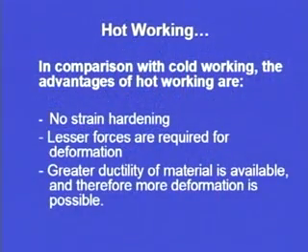Now, hot working, in comparison with cold working, has the advantage that there is no strain hardening. We have seen that strain hardening takes place in cold working, and strain hardening limits further deformation. When the material has strain hardened, the deformation or whatever changes we want to make will be limited. Lesser forces are required for deformation, as at an elevated temperature we have seen that the ductility is improved and the strength is reduced. So, lesser forces are required for deformation.